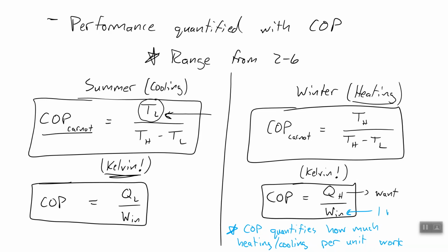If you put 1 kilowatt of work into the working fluid, and if your COP is 5, then you can expect to get 5 kilowatts of heat, of which 4 kilowatts will be heat we took from the cold space and moved to the hot space. 1 kilowatt of that heat will be the energy that we added into the pump, which was put into the fluid and then rejected as heat into our hot space. Kind of cool.